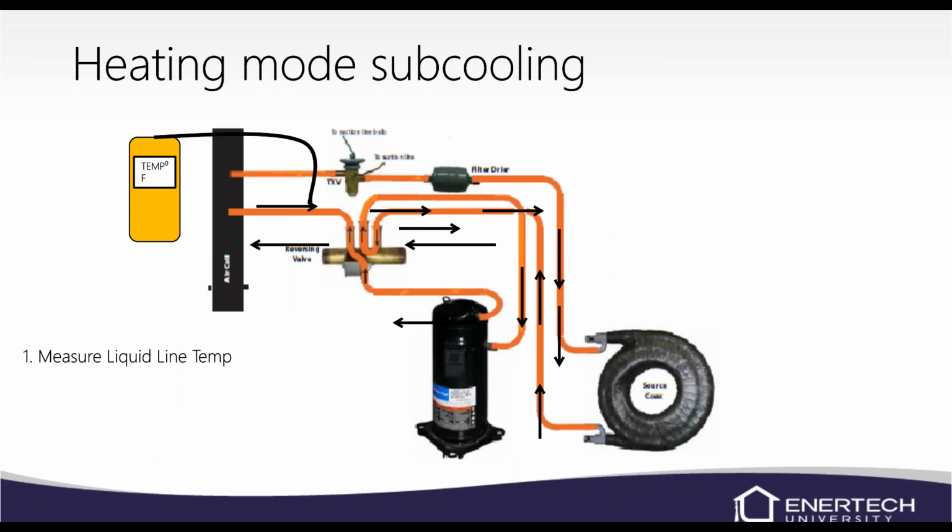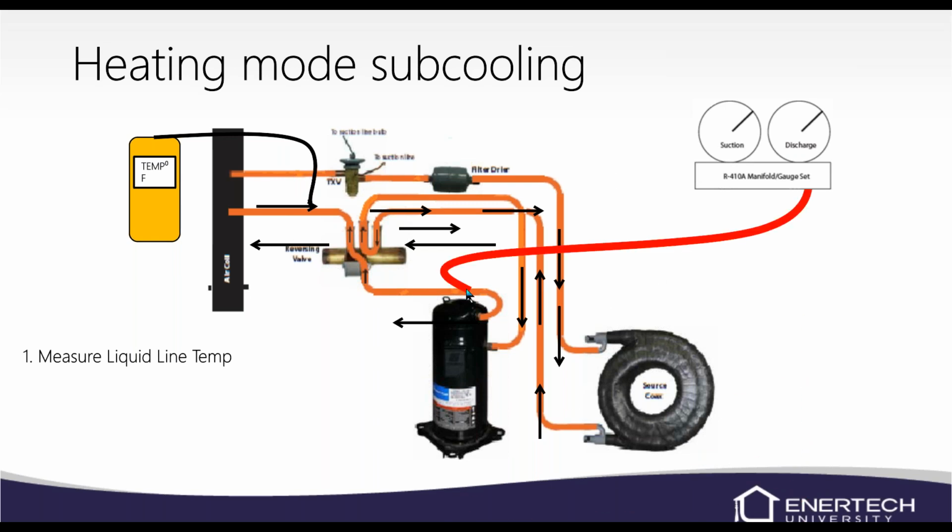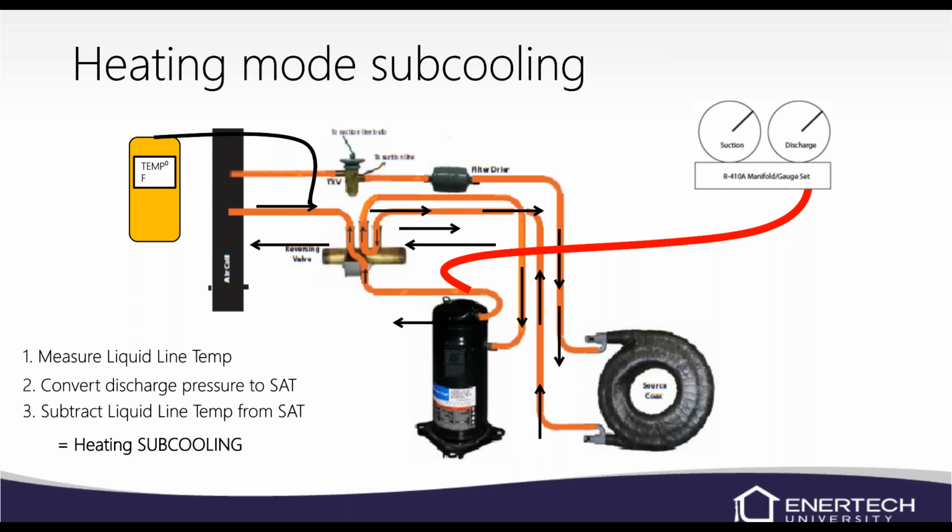Subcooling, now we're in heating mode. Actually, I need to move this up. It goes on this line here. And we're going to check that temperature, and then we're going to take our discharge pressure and convert that to temperature, and then we just do the math. And that gives us our subcooling.